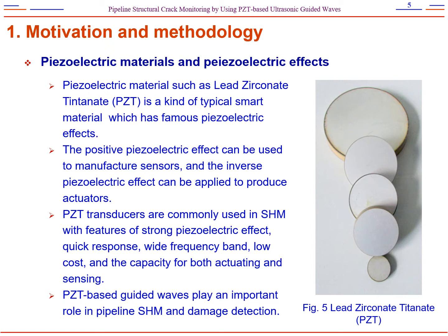So, PZT transducers are commonly used in structural health monitoring with features of strong piezoelectric effects, quick response, wide frequency band, low cost, and capacity of both actuating and sensing.